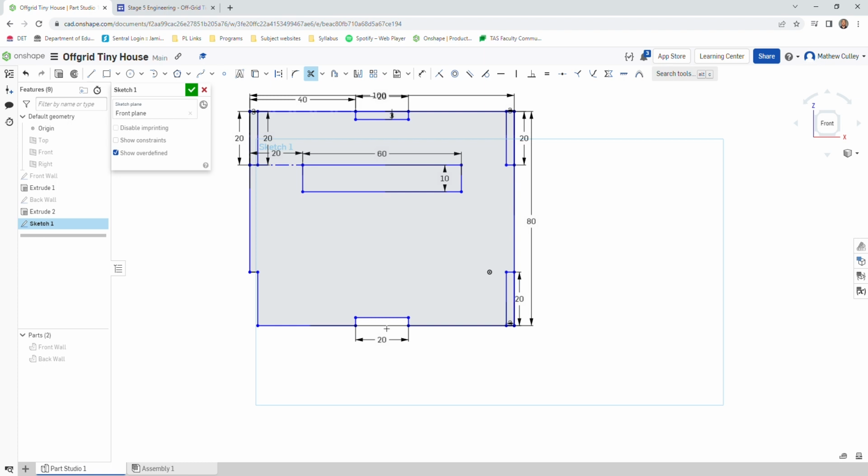Now we need to click that line twice because it has the outline of the rectangle underneath it there. Same with these ones here. Left clicking until we have removed the lines that we don't need. Okay, once your shape looks like this, we can now extrude it.